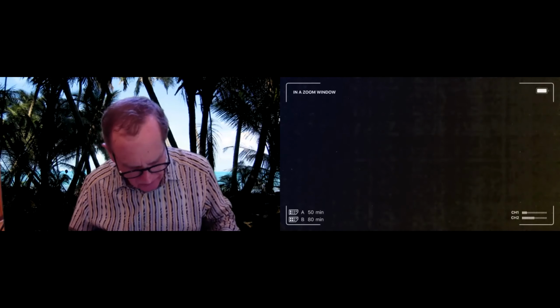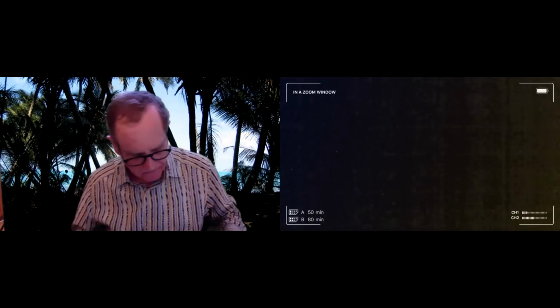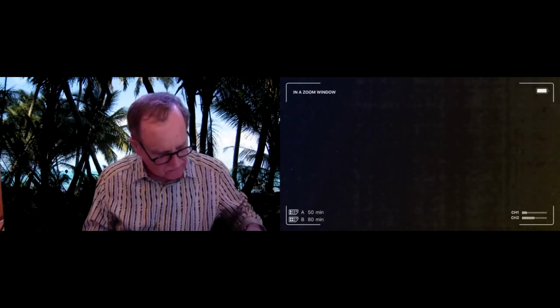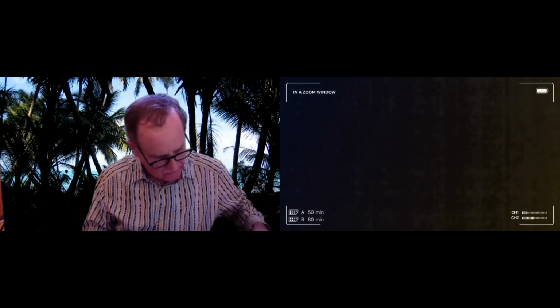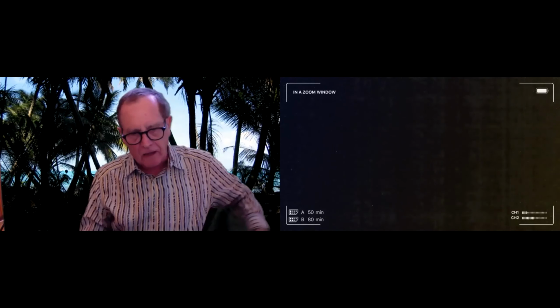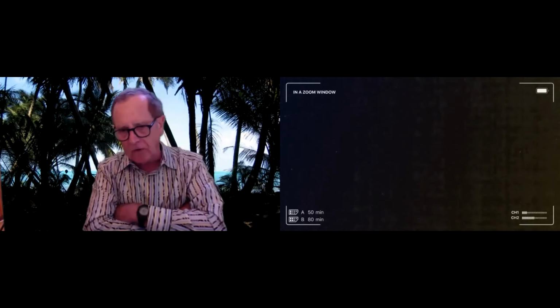Right, and just reading from the case study, if I may: the heat pump water heaters, which are used to raise the water temperature to that required for use, therefore consume only 20% of the electric energy normally required for all the water heating. So they're using solar thermal to heat the water, and if they need a boost, they're using the heat pump system. And it's stored on the roof, so everybody has access to hot water.